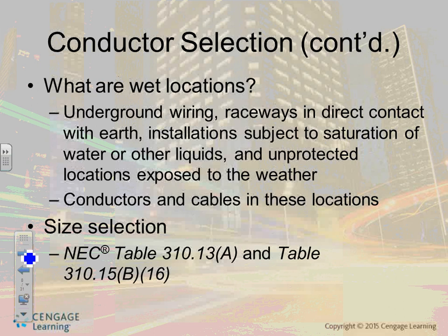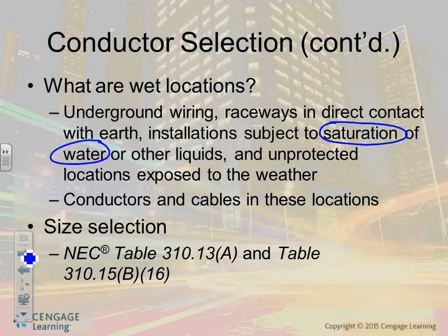Subject to variable. Here's the word that they use: saturation with water. That's how they define a wet location. Do you see my cup of coffee right now? If I pour it right on this table, would it become a wet location? Yes. Is this table normally saturated with water? No. Any room can be a temporary wet location, guys, right?